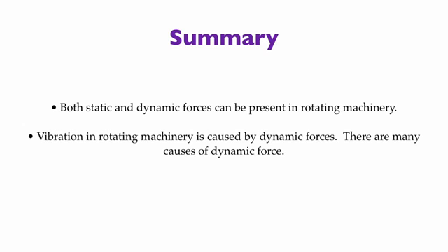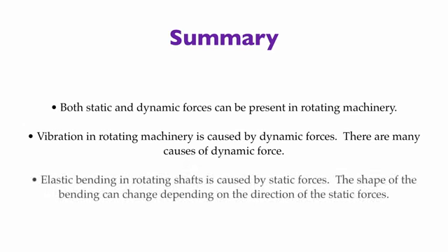Accelerometers, velocity sensors, and proximity probes measure vibration. They do not measure force directly. In addition to the dynamic forces, static forces are present also. These forces act in one direction and, if severe enough, can elastically bend or deform an object, like a shaft.